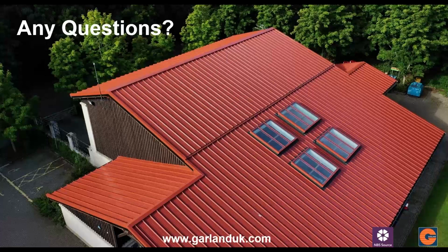These guys will attend site for you, and they will give you all the best recommendations that are up to industry trends, recent regulations and legislation. They'll guide you from initial site survey. They'll give you what's called a ramp report for us, and that will set out everything they find during that survey. If there's localized moisture penetration down through the installations we mentioned earlier in one of our precedent projects, it will define in that survey what needs to be done to get that project back up to standard and minimise any leaks. So that's the first step. And with your instruction, they'll form a specification, and that specification will ultimately give our best guidance on what we would recommend to do to that roof.